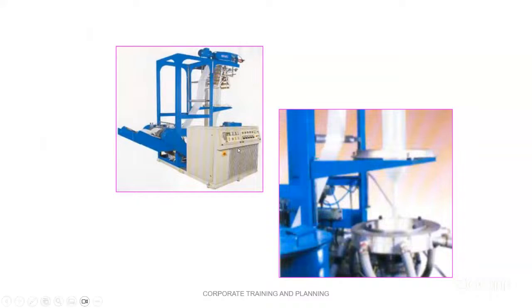See now, these are the plant pictures. See now here, the machine. It requires a higher floor, see the height of this machine, maybe two floors, three floors like that. See, this is an air ring, and this is a blower. Through this, very high cool air will pass outside the bubble, and therefore the bubble gets cooled easily, friend.